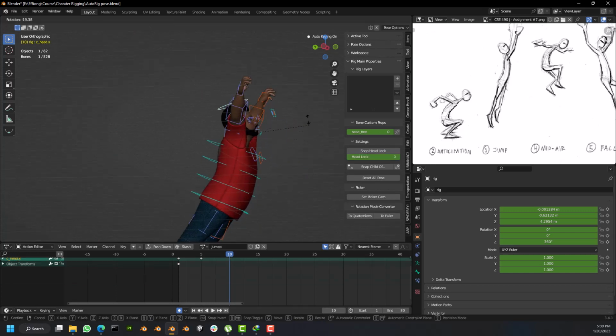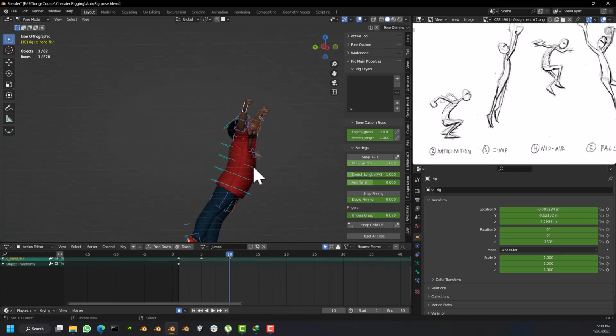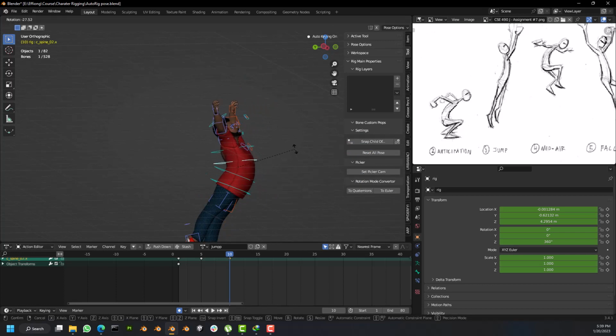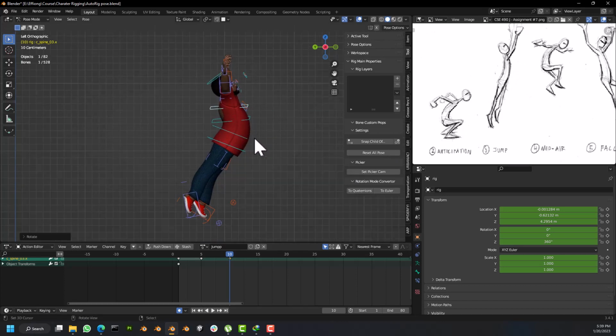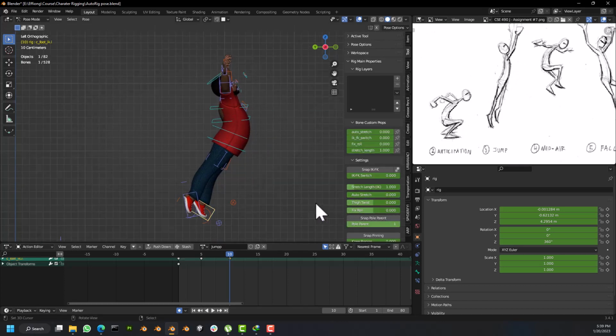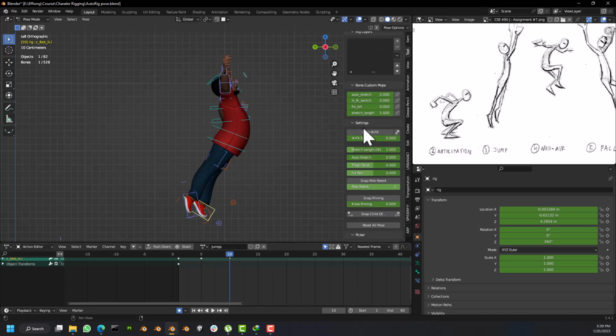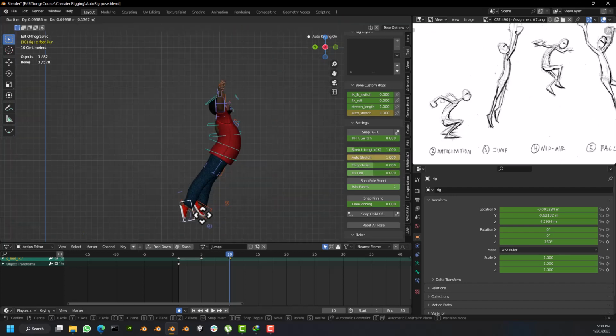So I'll lift the head up. Okay, I think I'll stretch this backwards a bit, just to have that arc. If you notice the arc here, just to have that arc. So if I look at it from the side view now, if you notice the leg, there is a stretch. So if you come to your tools panel and scroll down, the feet is in IK, right? So you just see auto stretch. So you want to put this at 1, select the left feet, switch auto stretch to 1. So let's stretch.